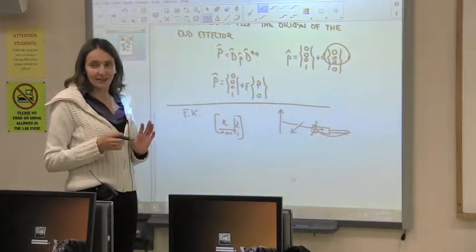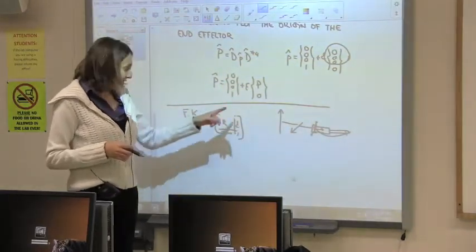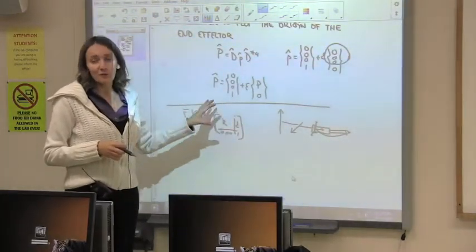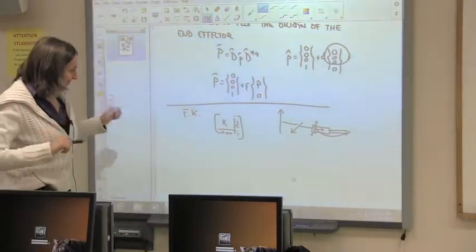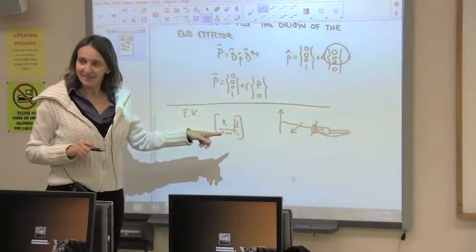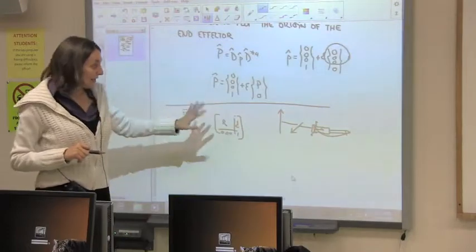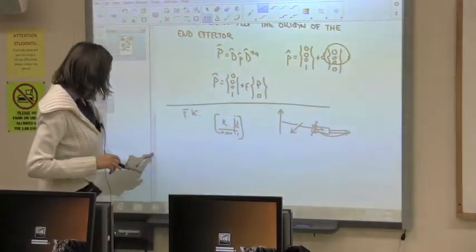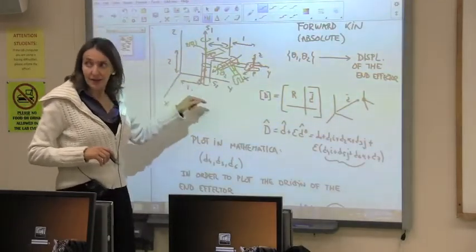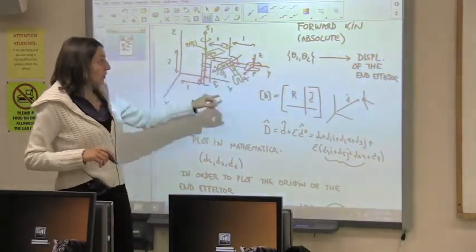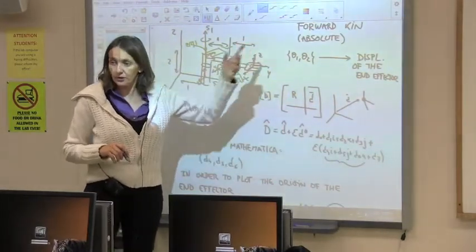It's kind of abstract, okay? You need to do one more step in order to apply it to points, because this is not a point. Well, it's a point of your group, and it's a different algebra. When we construct the displacement workspace, we use the forward kinematics from axis to axis to axis. Where we stop, this is the absolute displacement, okay? So that goes from one frame to another frame. And that is a displacement. So we go up to that frame that we define. Then from there you can measure any point, right?